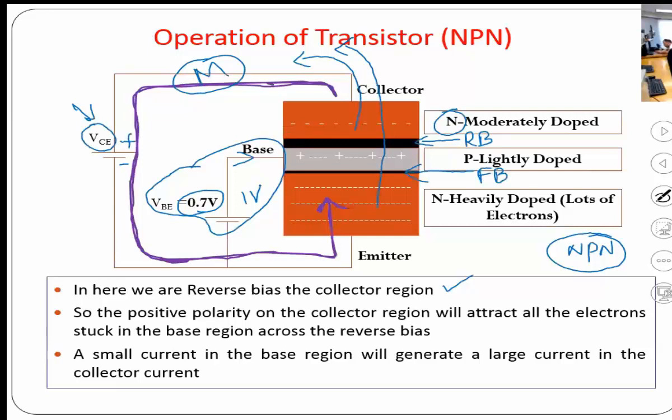So the base controls a little bit of current, but it's not needed. Depends on the application. You don't necessarily need to put a very high current through the base, because some transistors can easily be damaged. For example, if the requirements say the base should get at least 100 microamps, then that's all we aim for in the design. Unnecessarily, we don't go for high currents on the base because it's not a requirement.